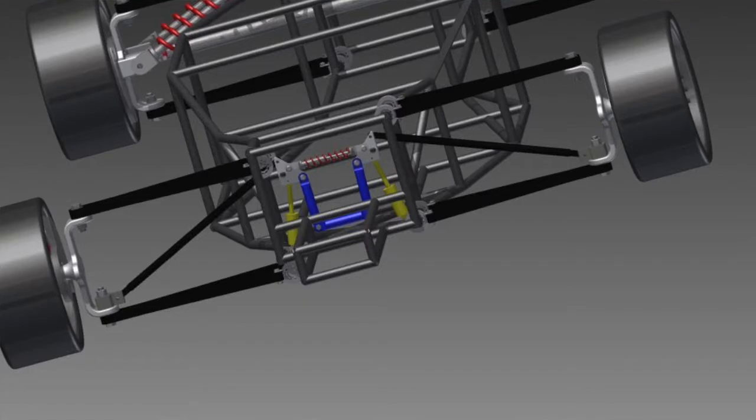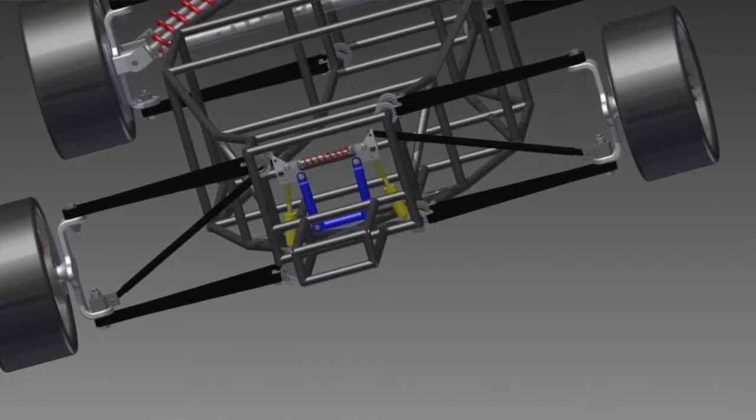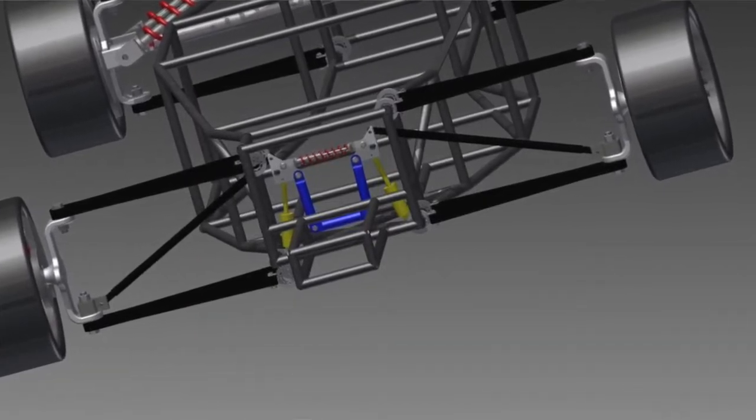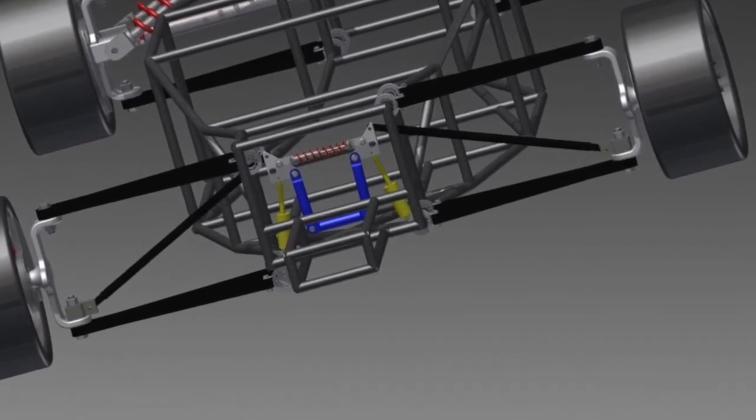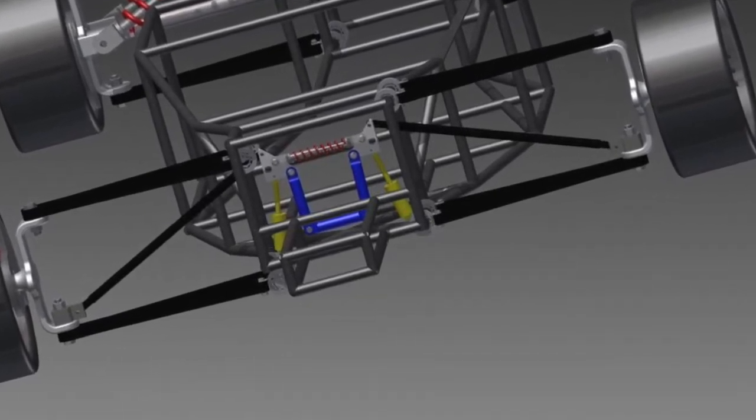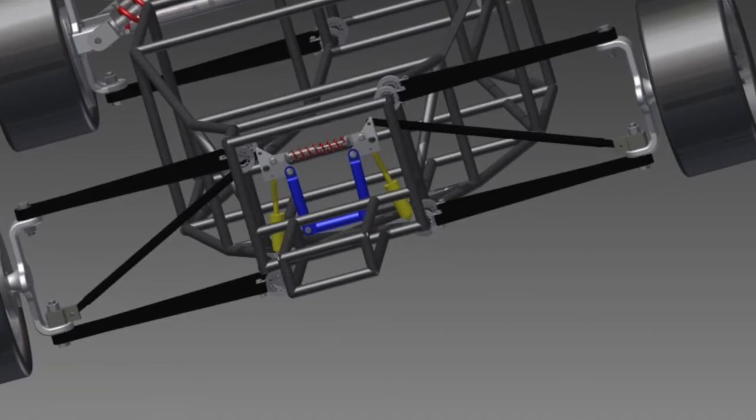Hi, my name is Adi, and I focused on 2 major components of the kart, the suspension and the drivetrain. The previous group did not have a functioning suspension. I redesigned our suspension based on a Formula One style pushrod suspension. The advantage of this design is that the components are collapsed to allow airflow through the side scoops. Also, the design produces more downforce through turns to provide better handling.